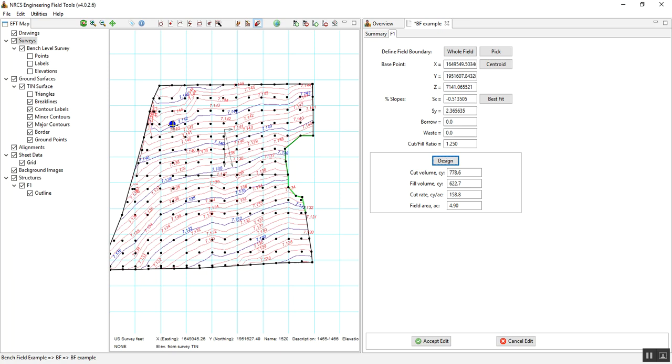We don't want that. We want it to slope this way from west to east. We don't want anything in the Y, so we're going to change the Y to 0, so no cross slope. I don't have the soils on this, but I'm going to guess 0.3 per 100, and we're going to design it. So no cross slope, Y 0. I'm going from west to east, 0.3 per 100, 0.3%.